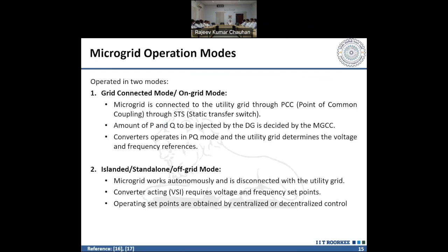You can increase the frequency by increasing the power which is fed into the generator. If it's a thermal generator, you require more steam to pass. In addition, there is another thing connected, called automatic generation control.